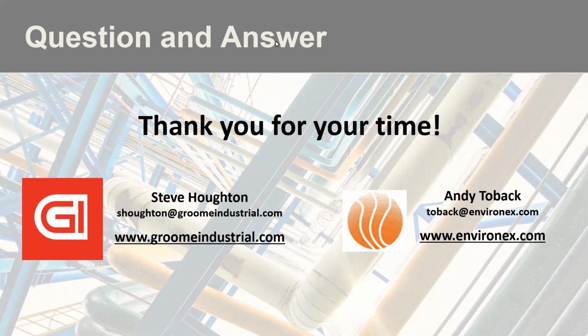There's a lot of moving parts. The plant has to operate at the same load. If there's any kind of blips in operation, we have to stall the test and wait till the system is back online, stable, et cetera. If there's a cal that's required, we wouldn't be able to test during the calibration period. And then there's stack testing issues. If you're in a hot zone, you're working with a glass probe. When you pull that probe out of the duct, it gets brittle. Sometimes they break.